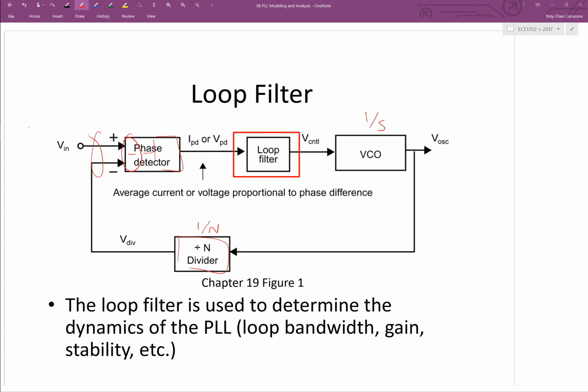You can actually make a quote-unquote phase lock loop very simply, technically speaking, without hardly anything in that loop filter. But what you end up with can track phase as long as there's some mechanism that's ensuring the VCO is at exactly the same frequency as the reference. If they're the same frequency, it'll put them in phase, okay? But what it won't do is let them track in phase and frequency at the same time. So a loop with one integrator in it is called a type 1 loop, right? And what happens if you put a ramp into a type 1 loop?